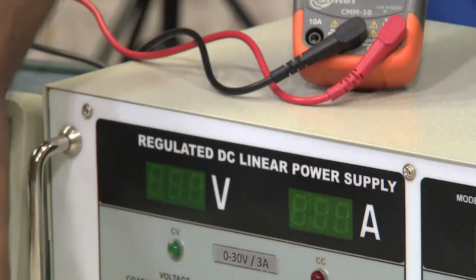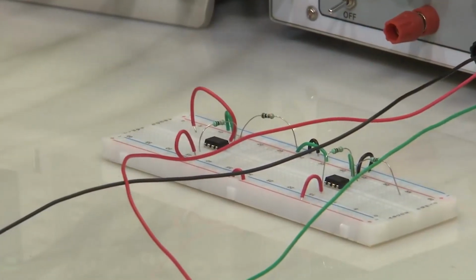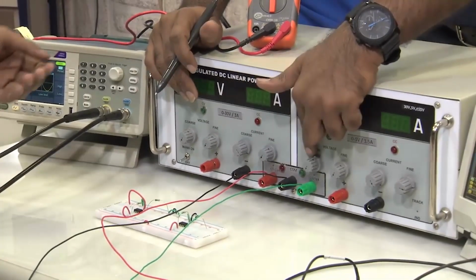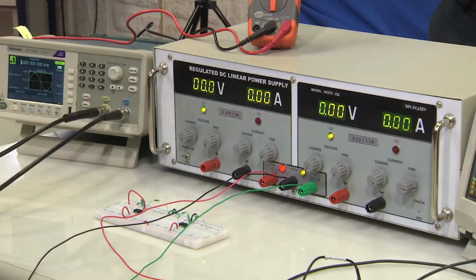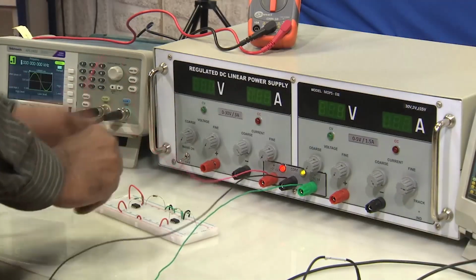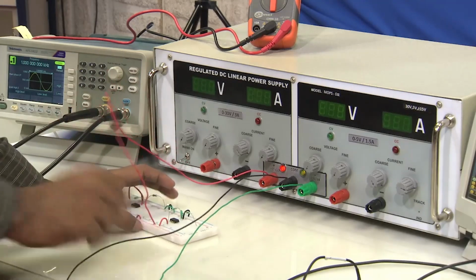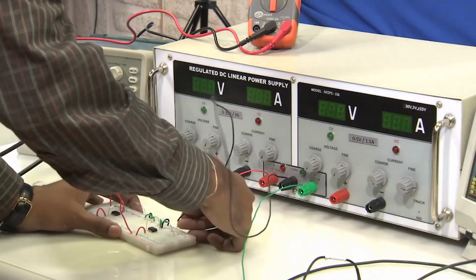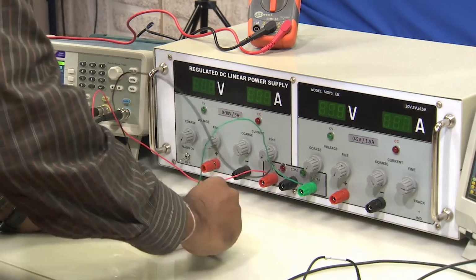So, let us see how we can do it. I am placing it here, right. Now, we have here on this DC power supply plus 15 minus 15. So, we can first connect it here, and then we can apply the DC power supply. First we connect, and then you should apply. Alright. So, what he is right now performing is connecting the bias voltages plus 15 minus 15 to the inverting amplifier using the op amp.